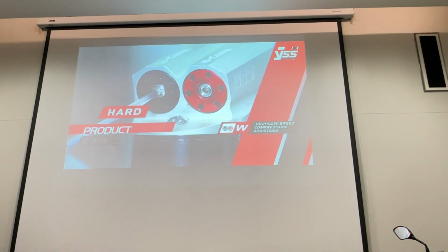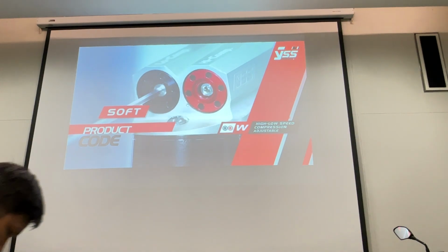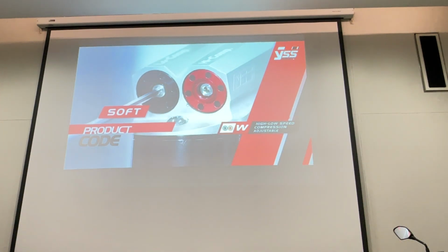W equals high-low speed compression adjustable. It is the ultimate compression adjustment developed from low speed, designed to allow the oil to flow through the control knob. This valve set will operate when the oil pressure is too high for low speed compression to handle, when the vehicle has a heavy bump. It prevents the vehicle from hydraulic lock.